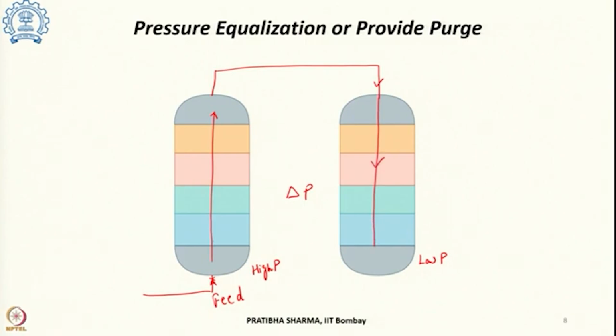So, this is a counter current pressure equalization step in which the hydrogen which can still be recovered from the first bed can be transported to another bed, bed 2, and this particular bed can be used for the repressurization for step number 4.